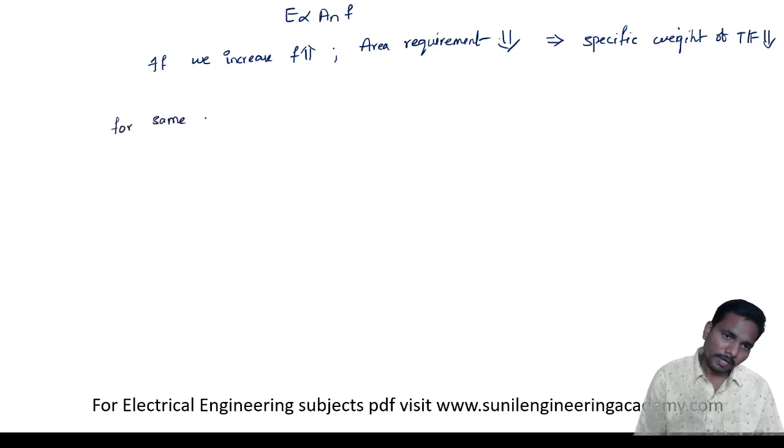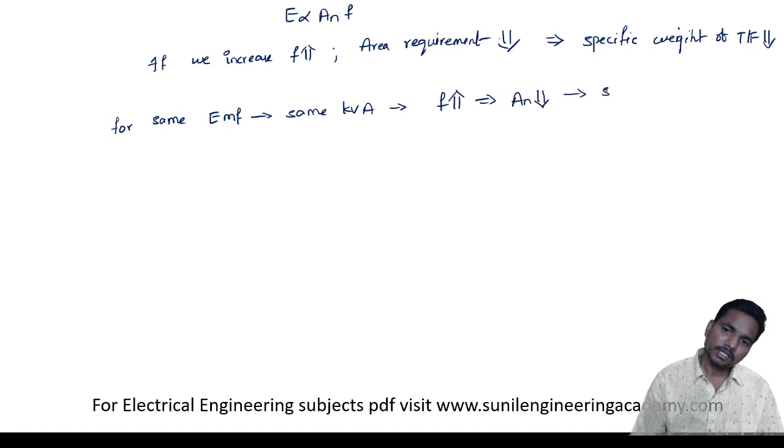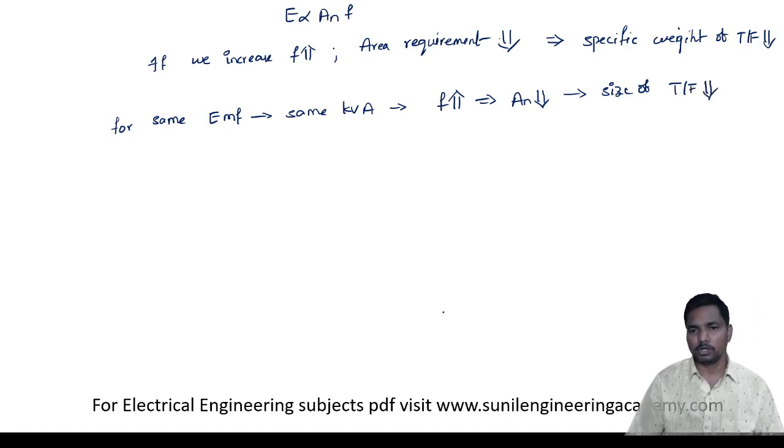So that means for the same EMF, which means the same kVA, if frequency is more, then the area of the cross section is less, then the size of the transformer is less, and it becomes portable. At high frequency, the size of the transformer is less.